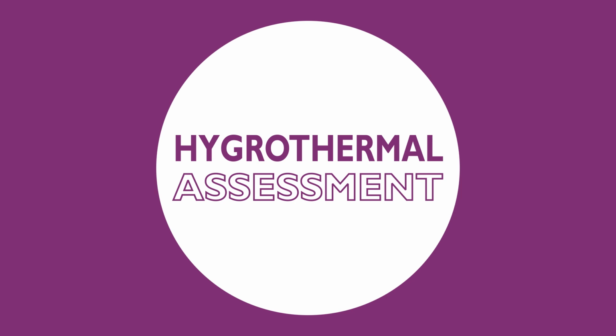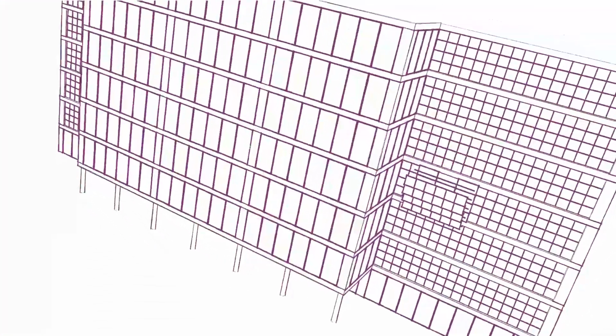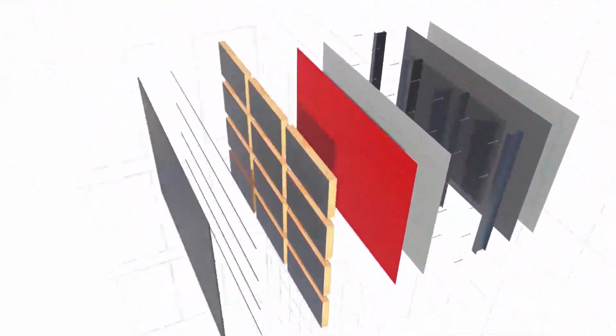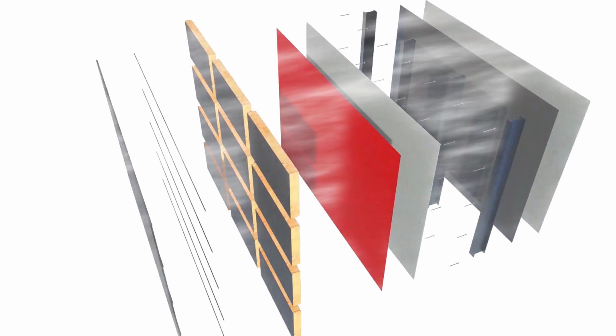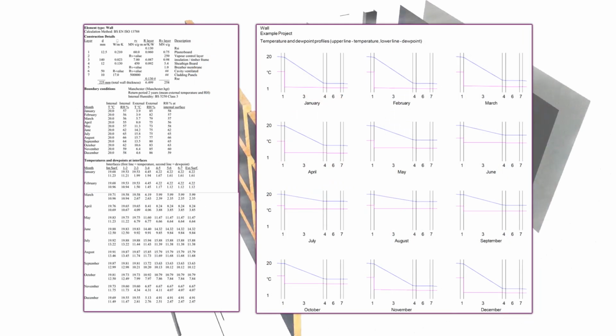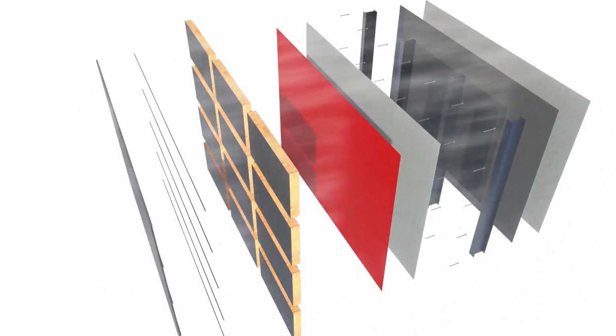To ensure our design adequately manages these complex interactions, we undertake a hydrothermal analysis of the building fabric using a software called WUFI. This breaks the building elements into individual layers and calculates the temperatures, moisture flow and degree of water storage at any point in the building fabric we choose to assess. Historically, a process known as the Glaser method was used to assess this. However, this method makes a few assumptions that limit its accuracy.